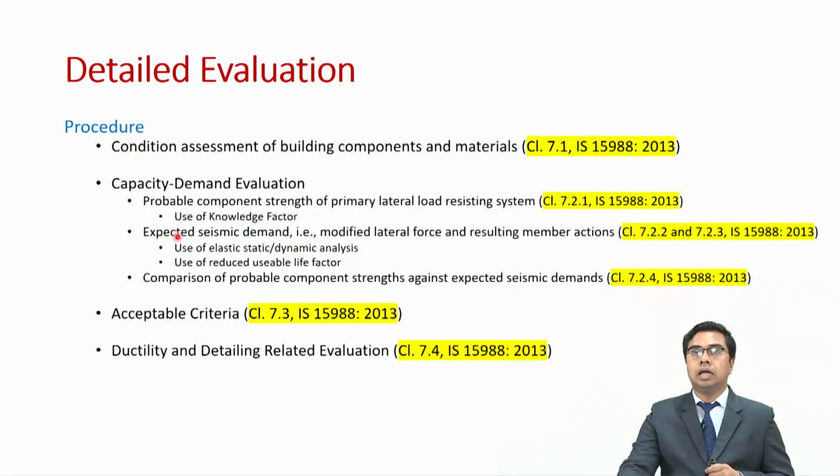Then we shall calculate the expected seismic demand, that is the modified lateral force and resulting member actions. This shall be based on various methods, whether it can be equivalent static method or the dynamic analysis method, and here we shall use the usable life factor, which takes into consideration that the existing building has a service life which is much lesser than a new building.